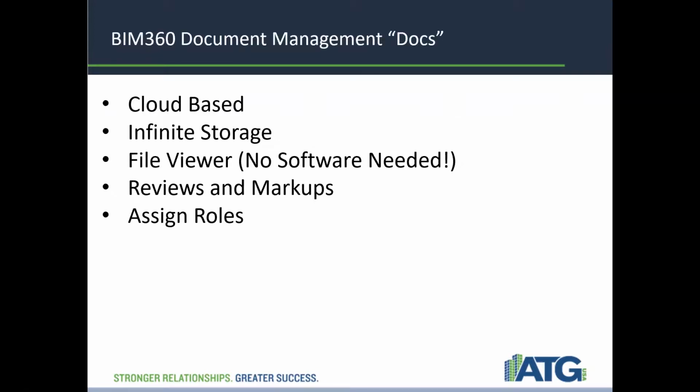So jumping right ahead, we have BIM360 Document Management, or Docs. This is a cloud-based platform to share files and view files. So anybody who has internet access can pull up the website, view the different files that can be put on there, and make comments. We can see what version they are from different revisions, and we can put different comments and markups, take measurements. If we've got a Revit model, we can do sectioning. It's an incredibly powerful tool, and all it requires is an internet connection. So you can do this on a tablet in the field, you can use your phone or any computer.